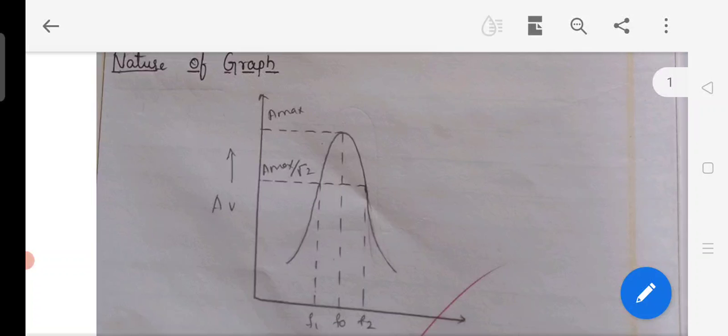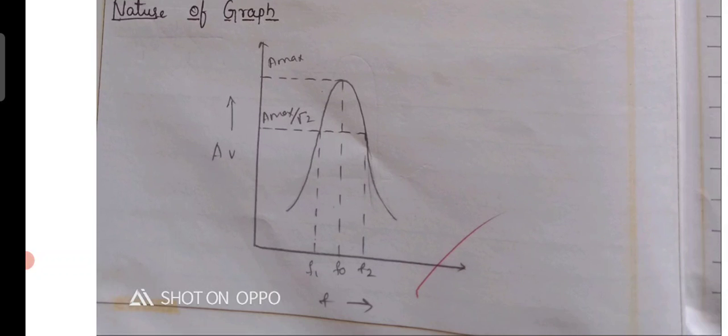What do I mean by gain then? The value of output to input, that is, the value of output voltage divided by input voltage, is known as gain. When we calculate that gain, we fix the input voltage as a constant value, then increase the frequency and obtain the output voltage. Finally we calculate the gain. After calculation of gain, we plot a graph of gain versus frequency.